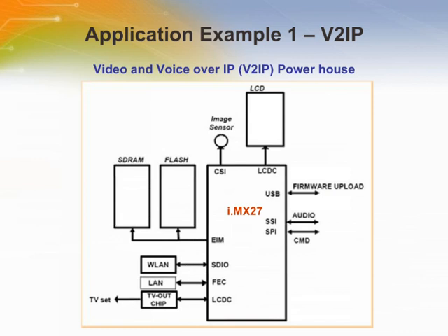The diagram shows a simple VoIP device requiring a minimum number of chips. When used in a typical VoIP device, the i.MX27 processor delivers the power to drive high-quality audio through wideband audio and wideband acoustic echo cancelers, in-call audio, and video recording on flash or other removable media, and decentralized three-way audio-video calls. It also has the potential to provide the ability to make VoIP calls with Bluetooth audio.